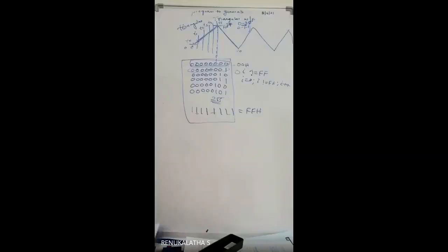Previously what we did, we placed IO0PIN equal to 0x000, an 8-bit value. We sent this and called a delay, and again we passed FF on this, only 2 levels. So it was so easy. Here you need to place 255 values into this IO pin register. So how do you do it? We cannot put the IO pin register in the loop. Can we? No, ma'am.